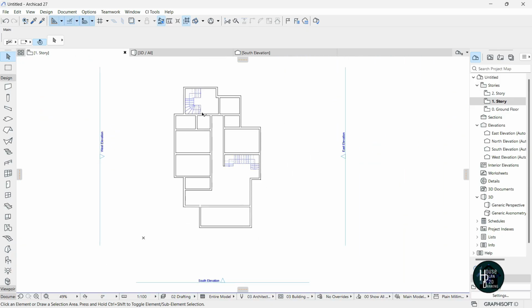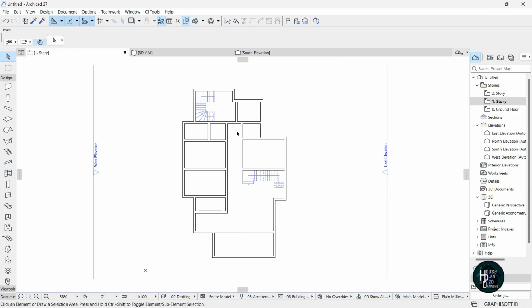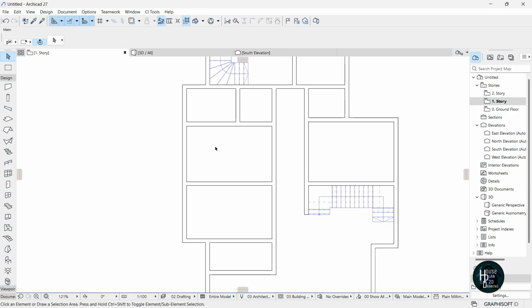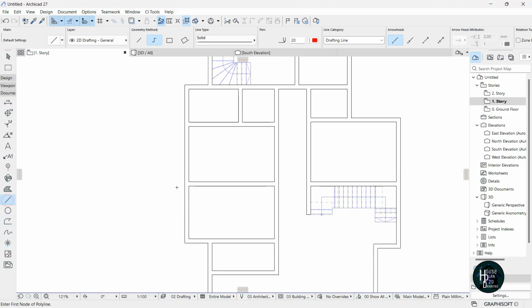So we are done with the sketch for the first story, but there's a little bit of adjustment that we need to make, for this room now. I'm going to click on the document section here, click on the line 2, click this edge of the wall here, drag it like this and give a distance of 5.2, click enter twice.